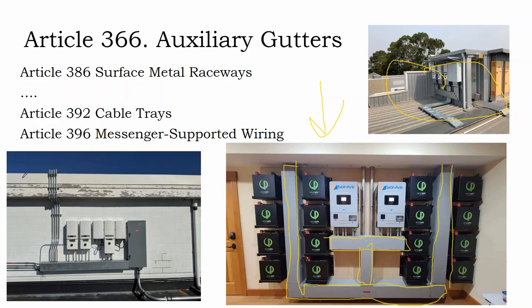And this depends on that DC wiring needing to be in metal. This is probably the DC side. If you wanted to be completely code compliant, maybe inside here you maintain some metal, or you make this particular box metal and have this be AC and have it be plastic, or these might be metal gutters. I can't really tell if they're plastic or metal from here.